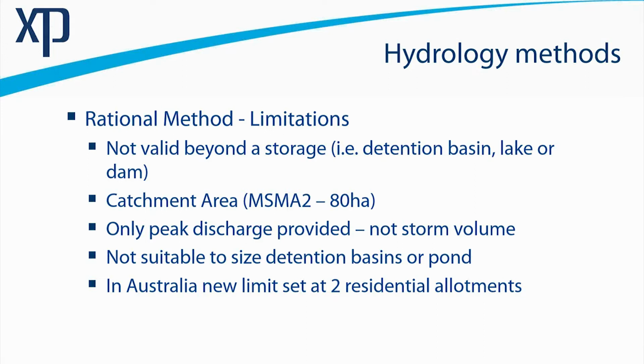Of course, the other key limitation is it only tells us a peak discharge rate based on the concept of the time of concentration, which means that it's not suitable to size detention systems. Now there are some equations to try and force the application of the rational method to size storage devices, but they're by no means rigorous relative to the data that we have available in terms of our design storm information or our ability to undertake calculations very rapidly inside computer packages such as xpswmm.